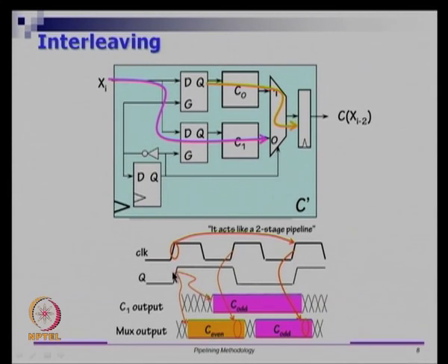So, what we have is there is a clock that goes every time period, and Q, if you notice what is happening to Q, there is a clock pulse that is coming in, and Q is going to toggle at the rate which is 1/2 of the clock. So, this is like a single flip flop. Q is going to toggle whenever the positive edge trigger comes in.